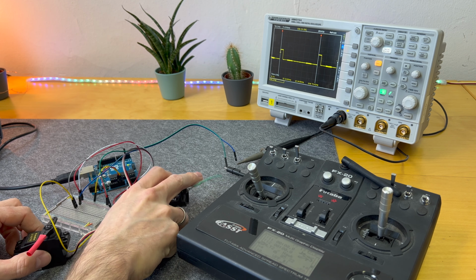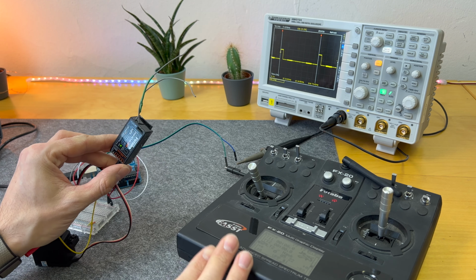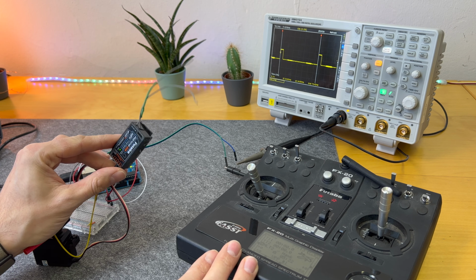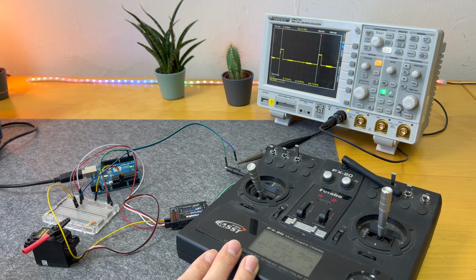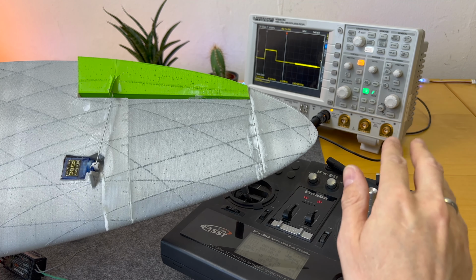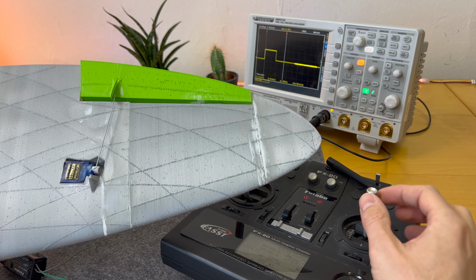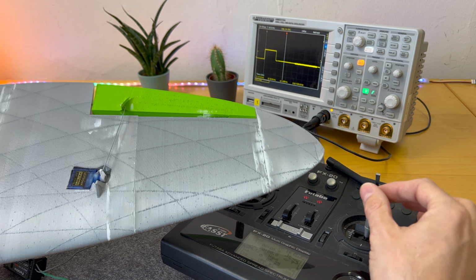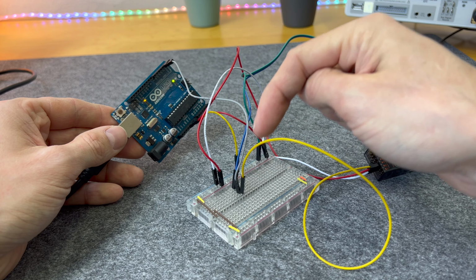This RC receiver here, which receives inputs from an RC remote, outputs a PWM-like signal. It actually outputs a high pulse of 1 to 2 milliseconds, each 20 milliseconds, so around 50 Hz. And the length of the pulse holds the information. How do we know? Well, they are typically used to control servos in RC planes, which then move flaps or ailerons of them. To read these values, we can poll all the time. We could use the Arduino built-in pulse-in function, but we can also use interrupts. So let's do that.